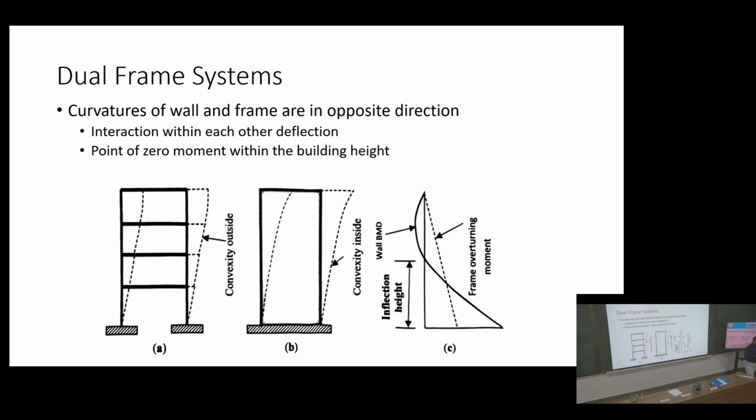And in a building, how do you calculate that inflection point? The shear force is maximum, but also the bending moment is zero. So you set up those equations and you can play around with these two. Clear so far?